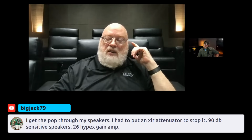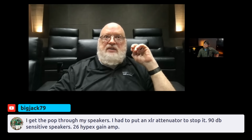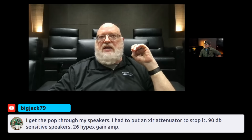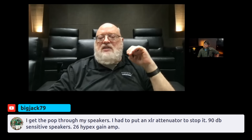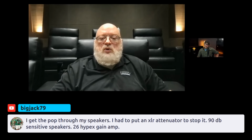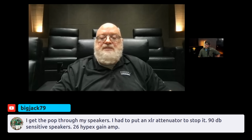But in the Amplitude 8, it's 19 dB, and I think it's about the same in the Amplitude 16. It might be 1 dB different, but it's basically around 19 or 20. I would guess that's probably closer to what you want. I guess he's probably getting a lot of hiss out of having 26. Potentially.